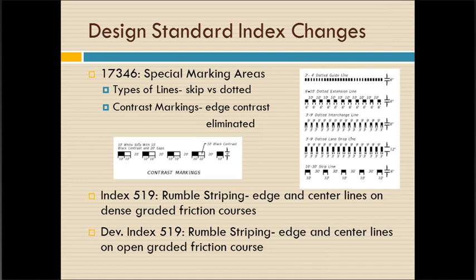So if you look at the MUTCD, it's got very specific guidance as to whether a line is dotted or whether it is a broken line. Now, we've always had a 2-4. We've always classified a 2-4 as a dotted line. But we've also taken 6-10 and 3-9, which we used to call skip lines, and we're now calling those dotted lines.